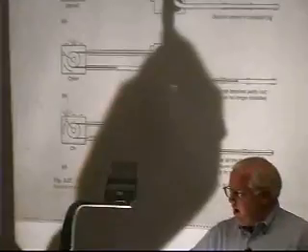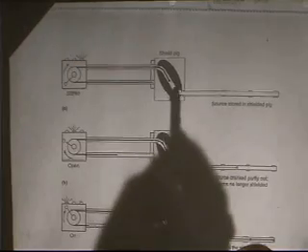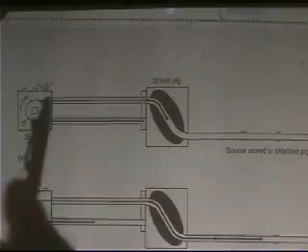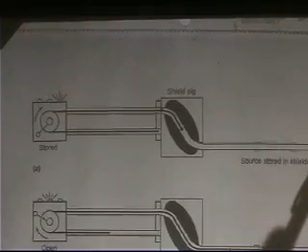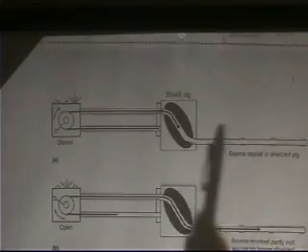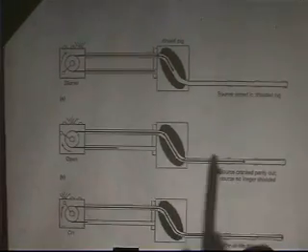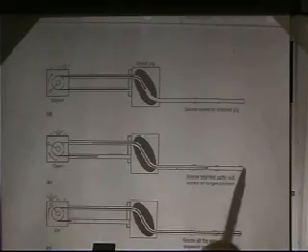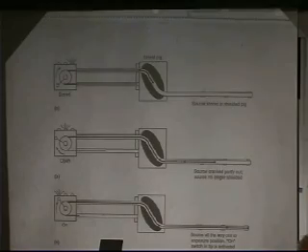Now, how do you do it? You basically have a cart, typically a lead-shielded chamber, and your radioisotope source is inside this, on a cable. You put the tube where you want to expose your film, and the guy just gets 50 or 100 yards away and cranks the cable, and the source goes out of the shielded, protected chamber. I pointed out in one of my classes that some of these things get to be very heavy.